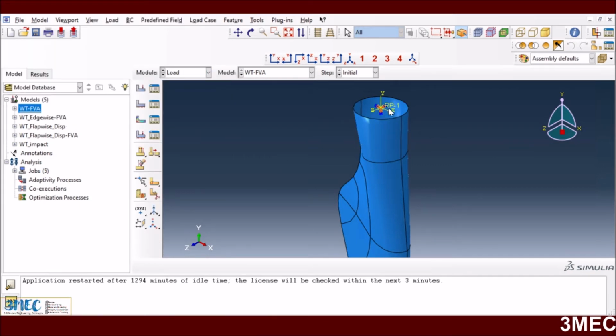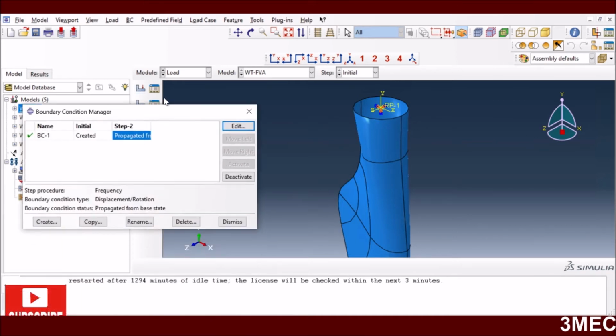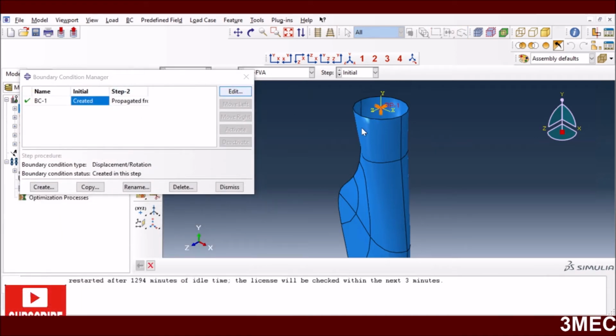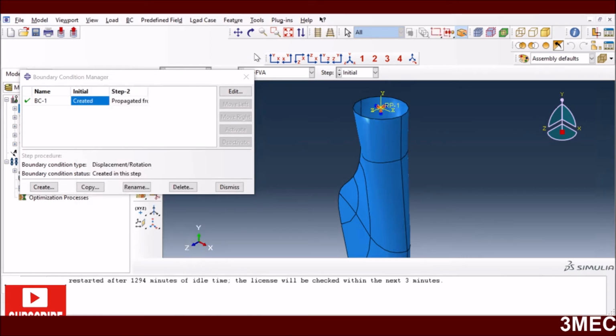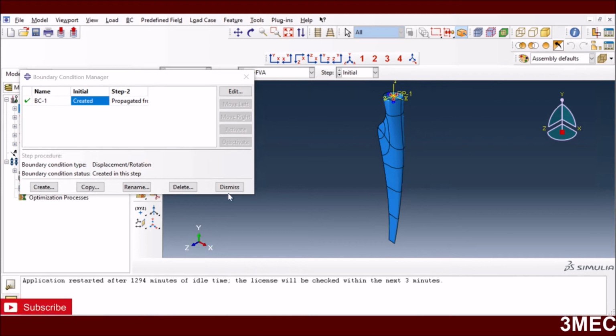And now what I'm going to do is fix this point here. So I'm going to fix my rotor blade with the so-called virtual hub. And for that, what I have done is basically, see, you have fixed all the degrees of freedom along this direction. In addition to this, I don't have any additional loading right now, so I'm not preloading my structure.